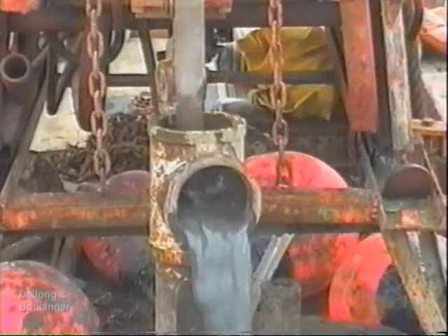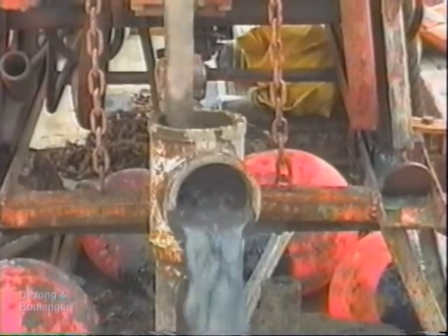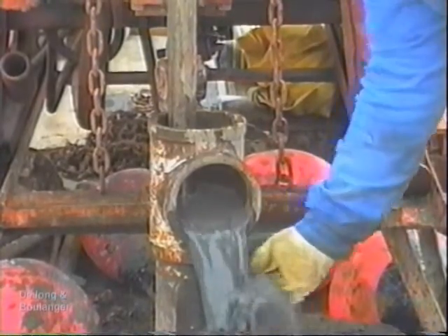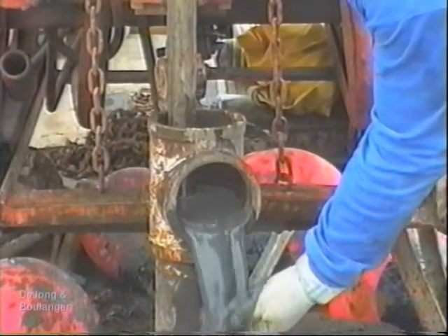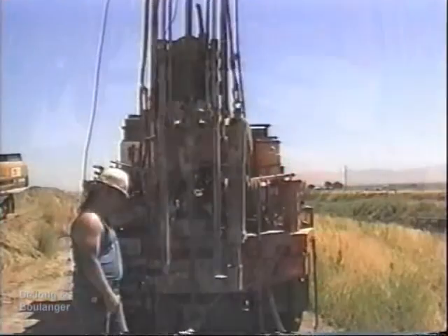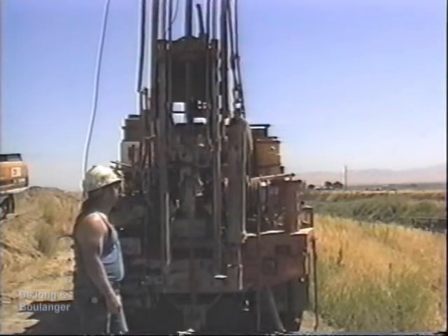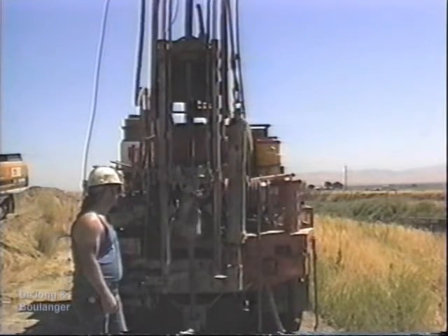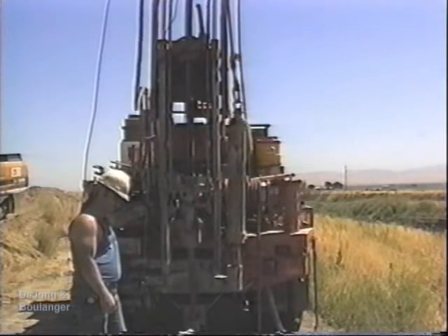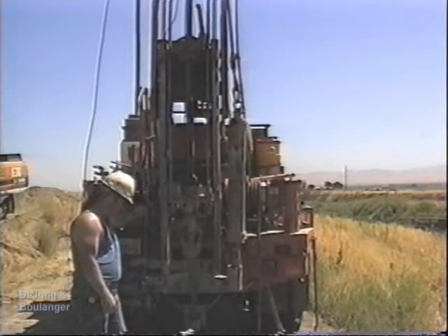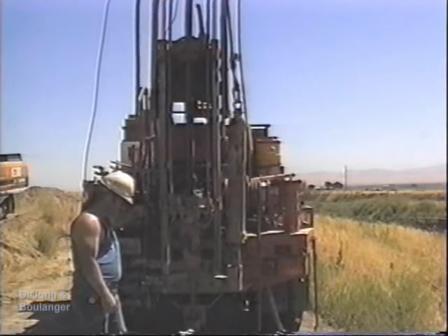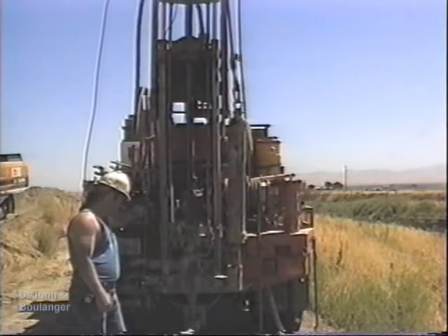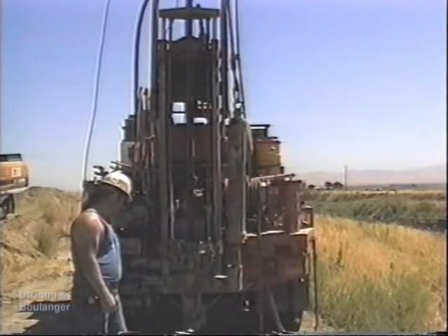It is very useful to check the cuttings as they enter the mud tank and to record any variations in the color or consistency. Such variations in the drilling mud can identify contacts between different soil strata. Operators may also detect changes in soil strata by changes in the drilling effort required to advance the hole. Sudden losses of drilling fluid can indicate that hydraulic fracturing has occurred or that a coarse free draining strata has been encountered. These types of information can supplement discrete samples and improve interpretation of subsurface stratigraphy.